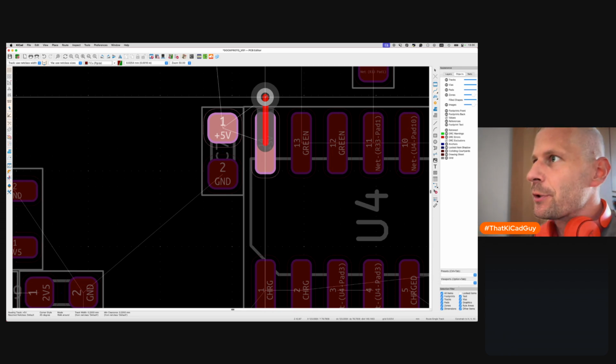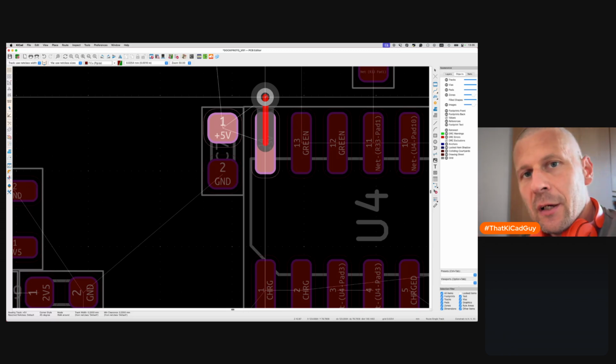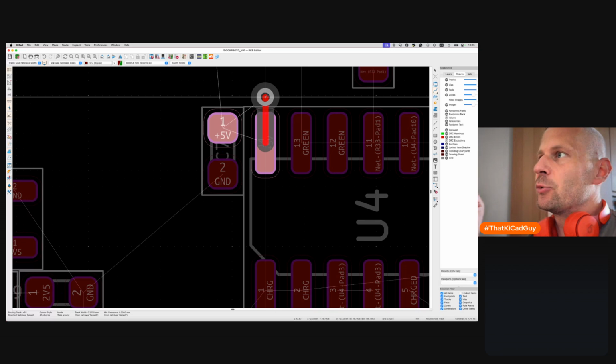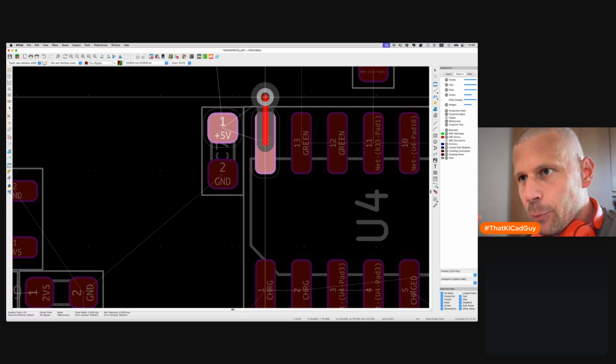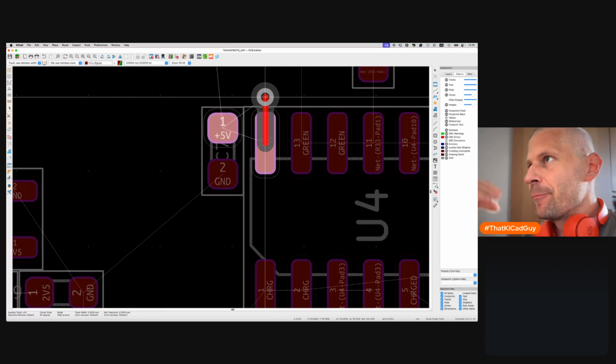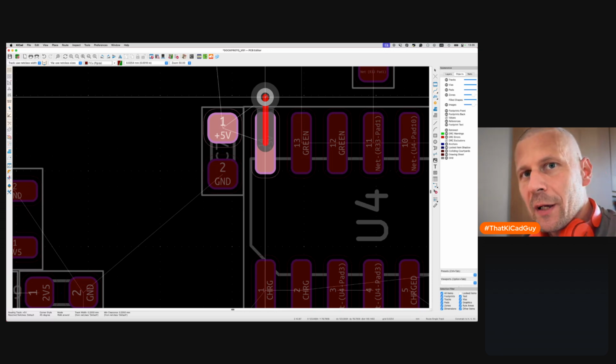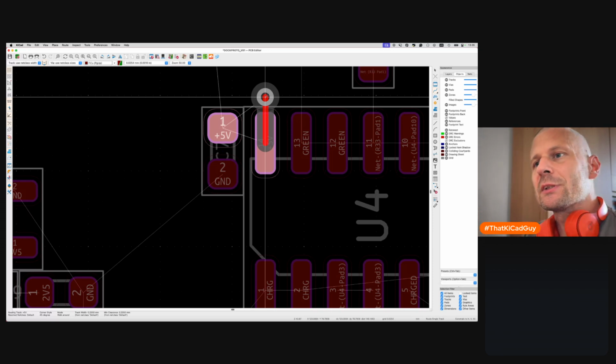This is quite important, and I recommend you set the solder mask expansion to a non-zero value, for instance 0.05 or 0.07, which is a standard expansion for solder mask. Then you can place your vias on better spots, to avoid the vias sucking out the solder from the pads.